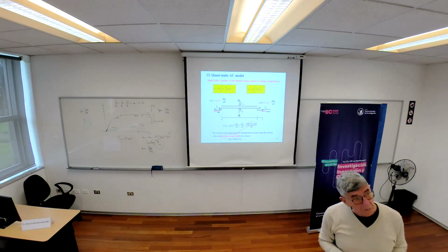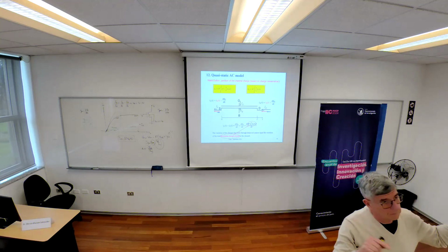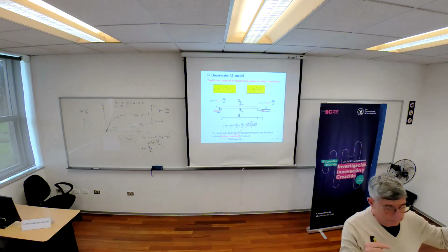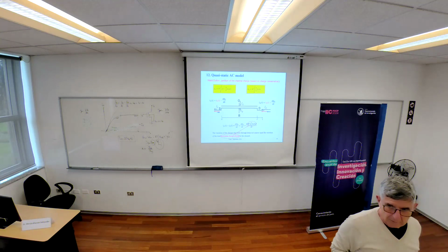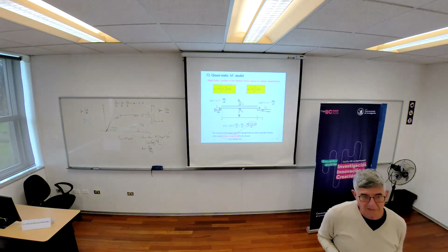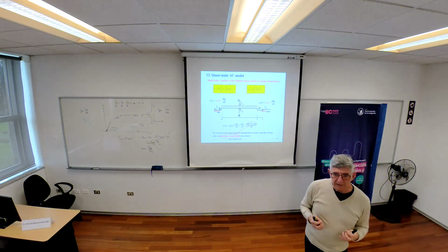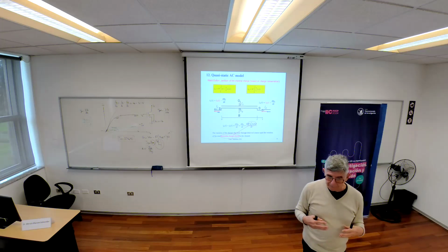If the transistor is in saturation, let's put 2/3 of the charge variation to the source and 1/3 to the drain. But the problem is that this model didn't conserve charge.